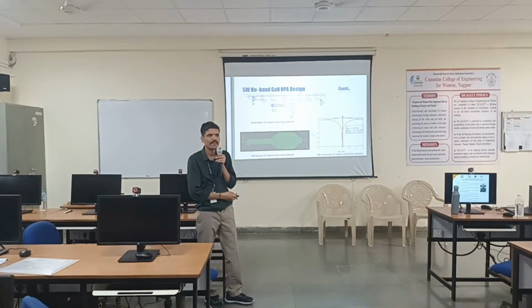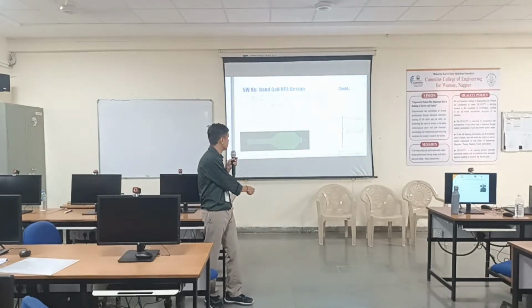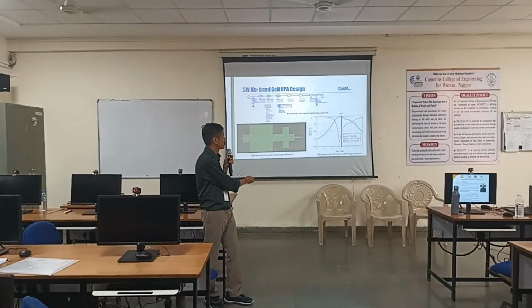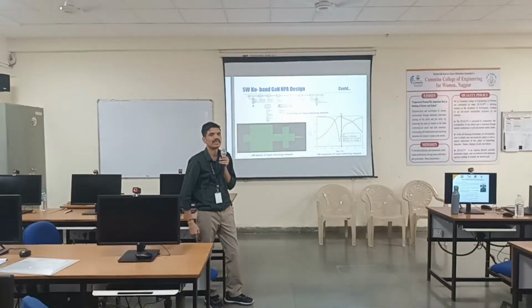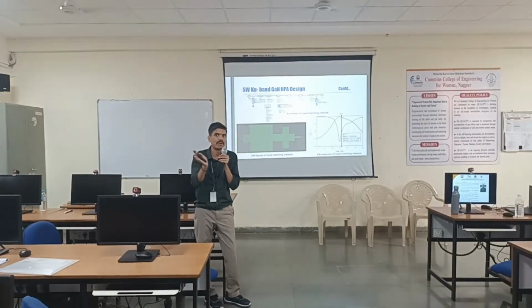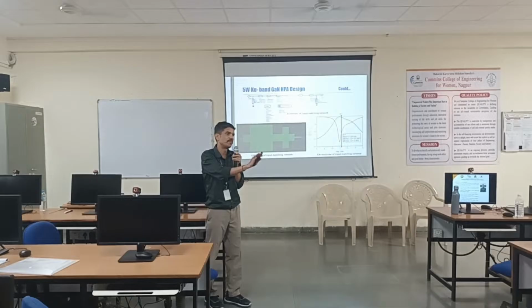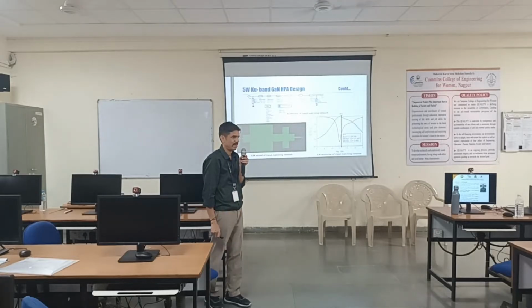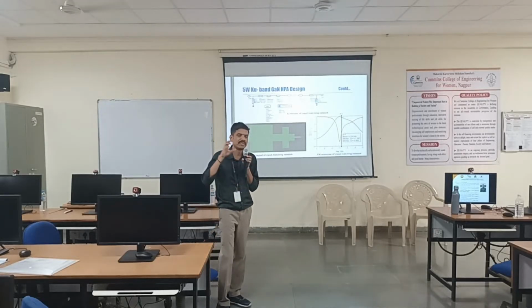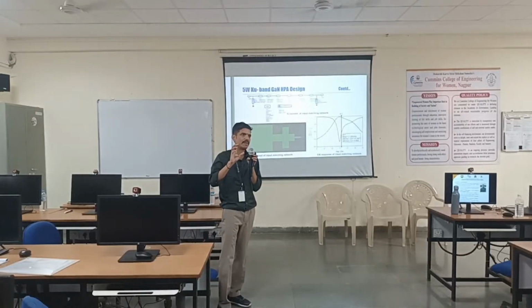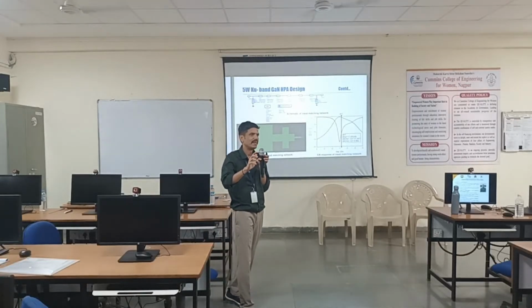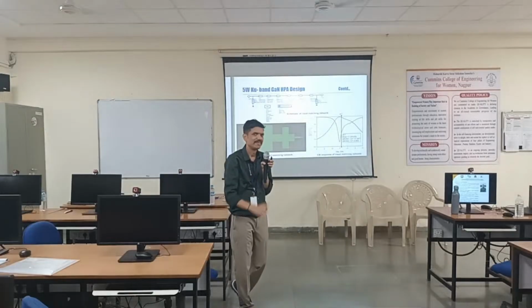Isn't it beautiful? But the same thing if you see in the earlier picture, gain is so sensitive to the input matching network. You cannot separate the OMN and IMN. They both will contribute to the PA performance. Earlier you said that PA design means the design of OMN and IMN. Now I am trying to tell you that it is more about IMN.